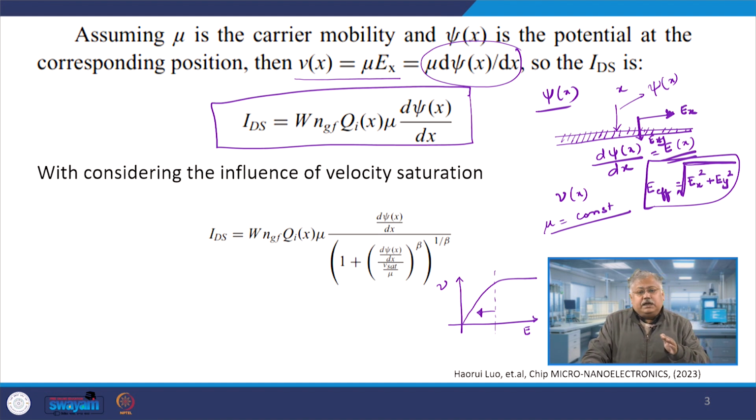It increases in a linear fashion, then it becomes non-linear in nature because of that drag, and the time comes when the drag becomes exactly equal to the force due to the electric field, and that's where the velocity becomes constant. So, this is the meaning of constant velocity saturation. So, velocity saturates basically, and therefore the current also saturates somewhere near this point.